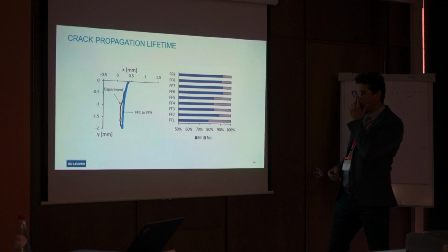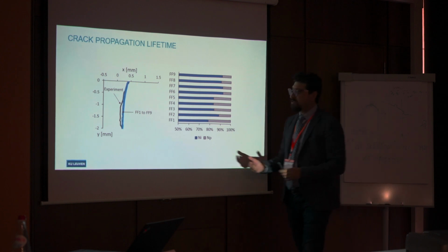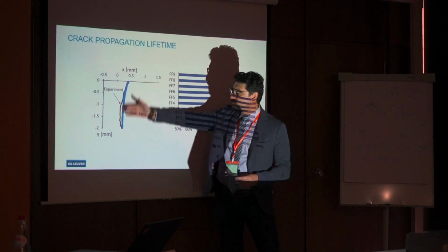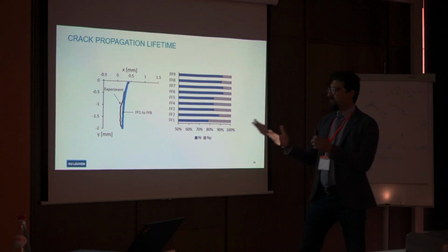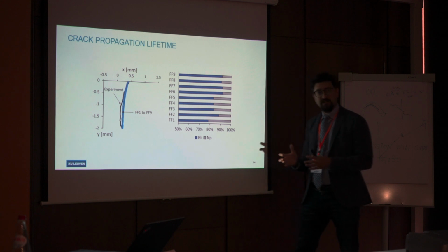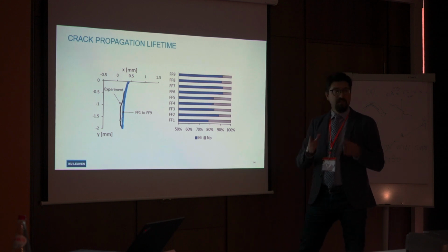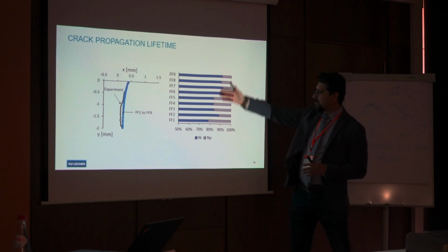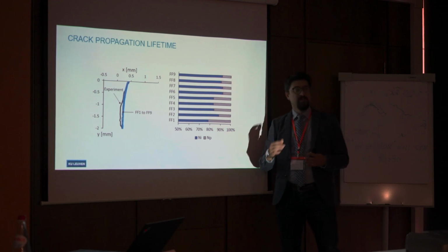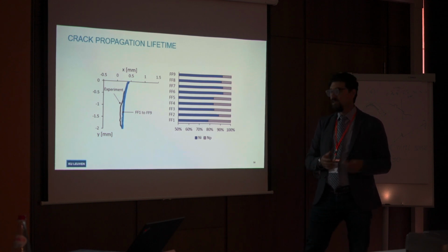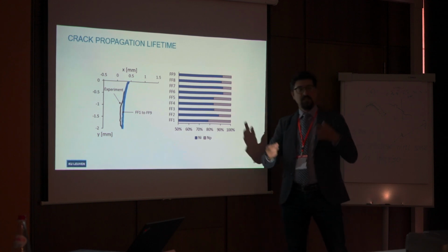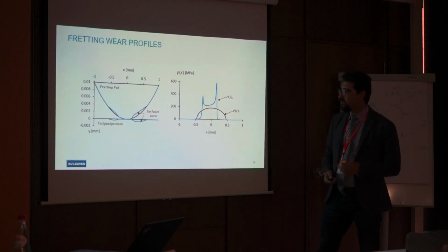So we tried to apply that to other tests, from 1 to 9, and we see almost the same behavior for all of them compared to the experimental data. Then we separated the crack initiation from the crack propagation lifetime. When I say crack initiation, I mean up to 0.1 millimeter. And then we more or less saw that around 85 to 90% of the total lifetime is spent in the crack initiation lifetime. So the crack propagation is a small part of the total lifetime.